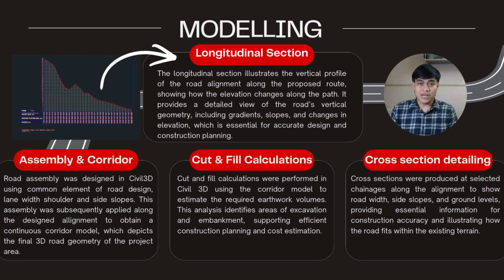The third one is cut and fill calculations. Cut and fill calculations were performed in Civil 3D using the corridor model to estimate the required earthwork volumes, and this analysis identifies the area of excavation and embankment, supporting efficient construction planning and cost estimation.